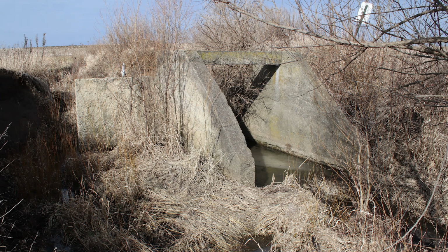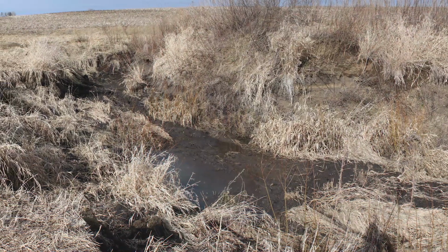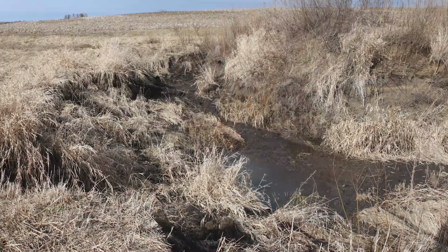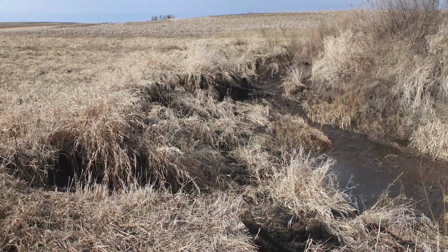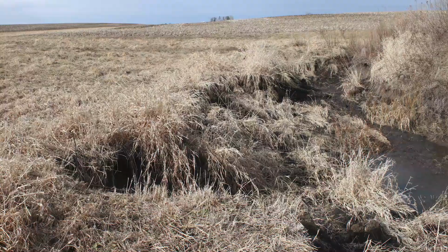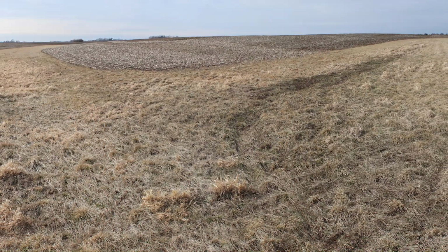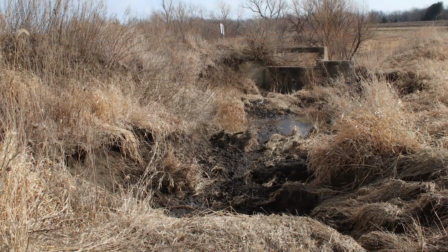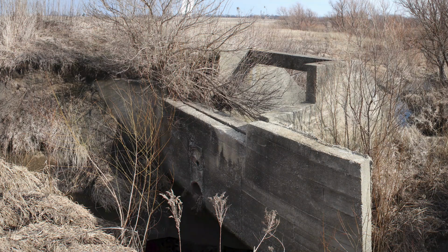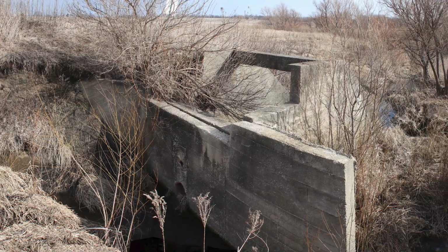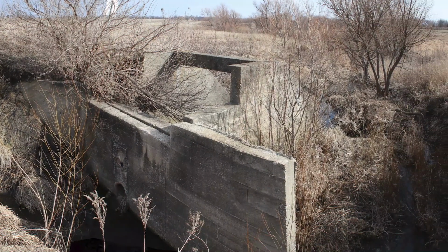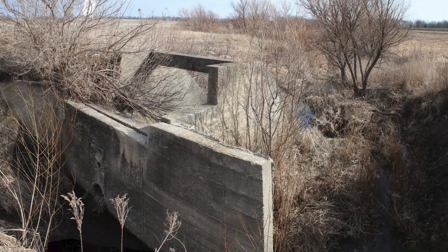The ditch has now bypassed the structure and is working its way up into the grassed waterway coming from the field. This practice failed because it was severely undersized for the amount of stormwater runoff it experiences. Runoff from more than 800 acres flows to this point. As runoff from storm events approached this location, the flow would become very deep as it tried to pass through the narrow structure, sometimes higher than the concrete wing walls. Once flows begin overtopping those wing walls, the soil around the wing walls begins to erode. Eventually, the ditch cut its way around the structure.